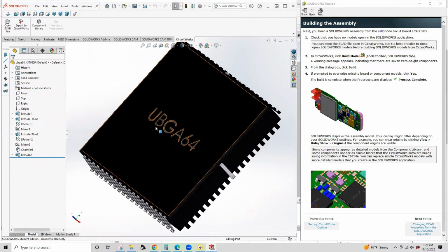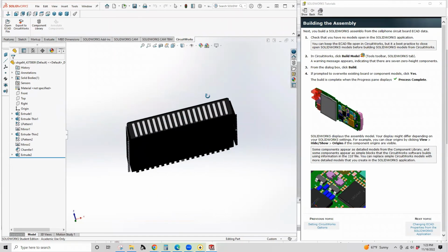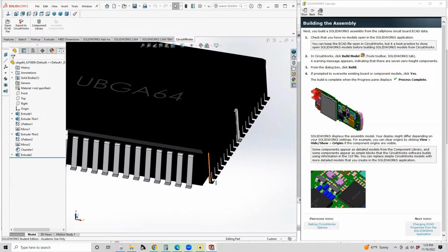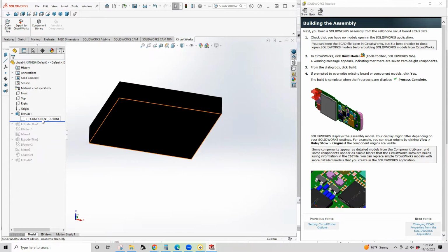Okay. So we'll take a look at this one because there's supposed to be another variation of this, but I guess that one's just a far more simple representation. So this is one of the few areas where we'll see this technique used. So starts off, you roll back the feature set as an extruded rectangle. Then we have a thin extrude.